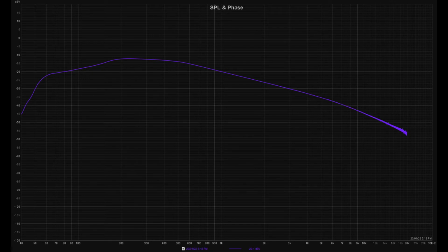And this is how it looks after only turning the equalization on and off, resetting the equalization options from the menu on the device. So there is something at the beginning that is not set up properly, and by turning the equalization on and off, it sets up the DSP properly.